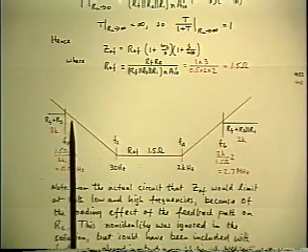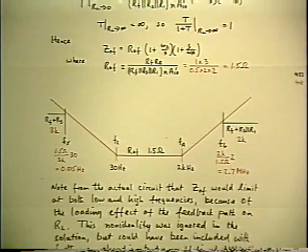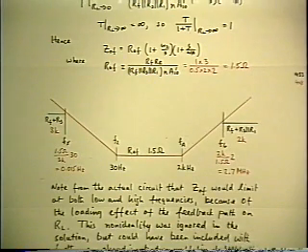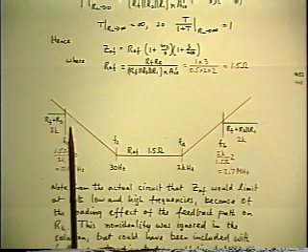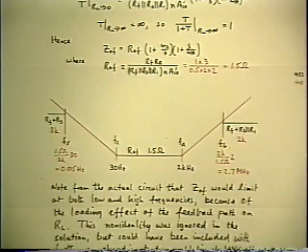We don't care what happens at 15 millihertz or 2.7 megahertz, because we know very well that the basic model we started with has fallen apart long before you get to those frequencies anyway. Remember, we've included an output power transformer and modeled it with the turns ratio of n. And the transformer certainly is not going to have a conversion ratio of n at 15 millihertz or 2.7 megahertz.